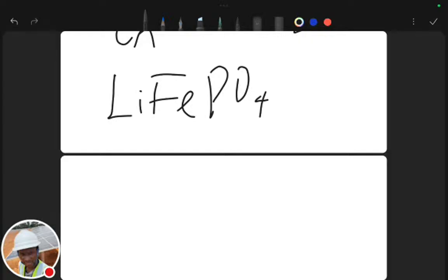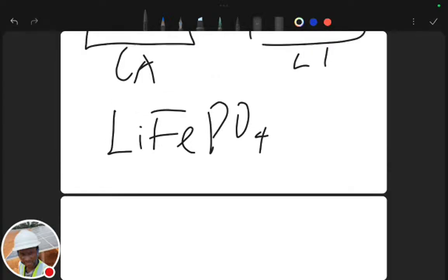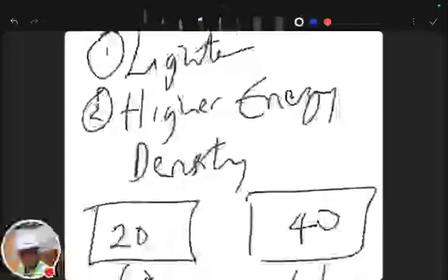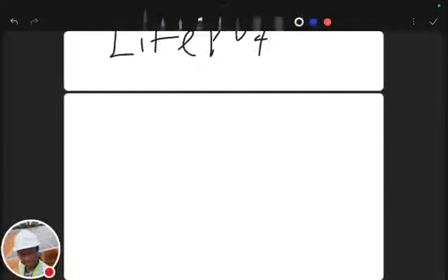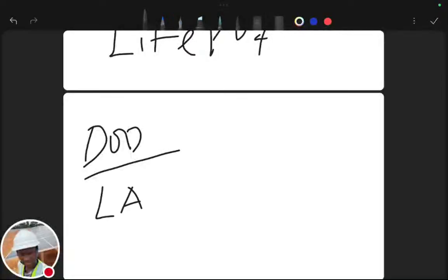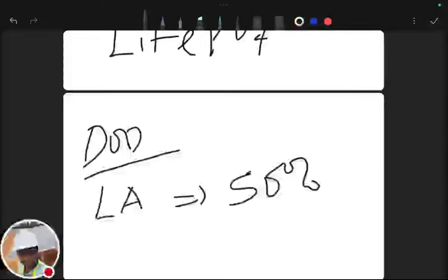All right, so let's talk about the battery parameters. And before I go again, let me talk about another thing that differentiates lithium from lead, and makes lithium actually better. You have the depth of discharge, DOD. For lead acid battery, that is usually around 50%. So imagine you are only advised to use your battery from 100 to 50%. Don't use it below 50%. That's how lead acid are.